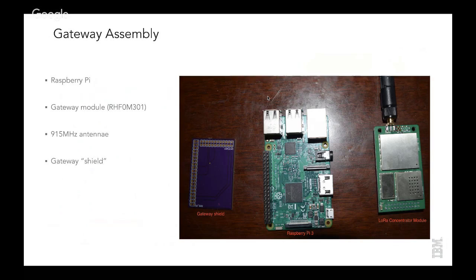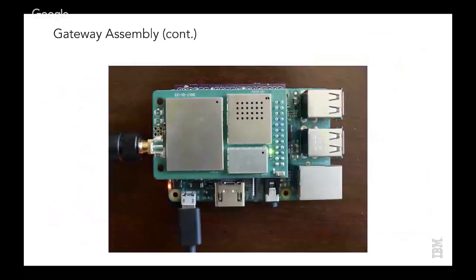Essentially, initially I used wires to connect the relevant gateway pins to the GPIO, but it was very difficult to debug and things could become unplugged very easily. So I switched over to a PCB shield, which you can see on the left-hand corner. This is what the final result looked like after setting up with the PCB shield. I just had to solder the gateway shield to the LoRa module and then insert some header pins to connect to the Pi.